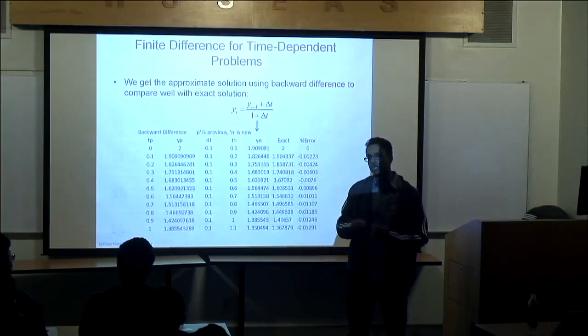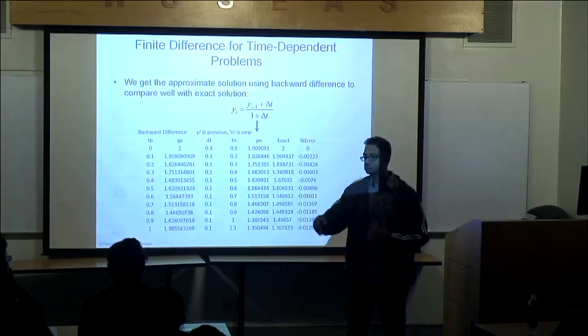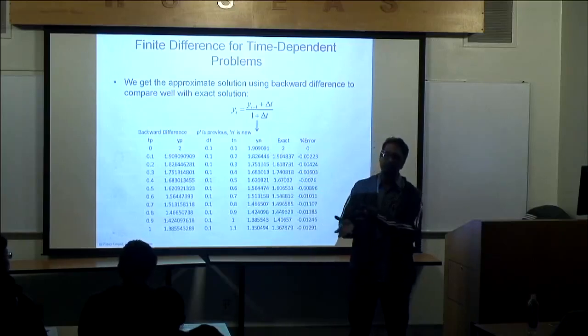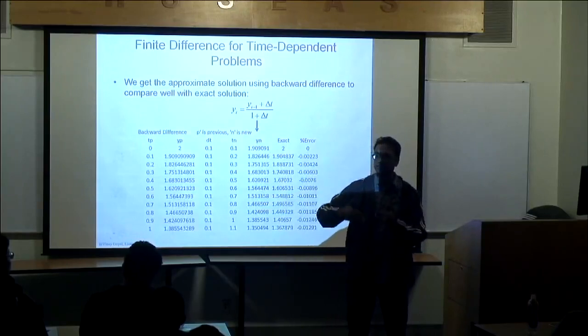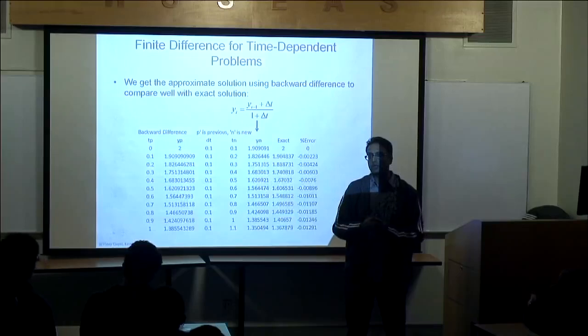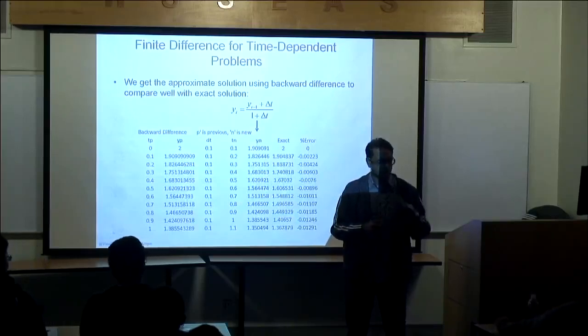And you have to look at the problem you're working on. Maybe the loads that are applied to the structure are slow over time. Or if it's slow over time, maybe the structure won't have time to respond. In those scenarios, you can look at larger time steps because things are not changing very quick, right? I was working on a project where things were happening in hours, right?